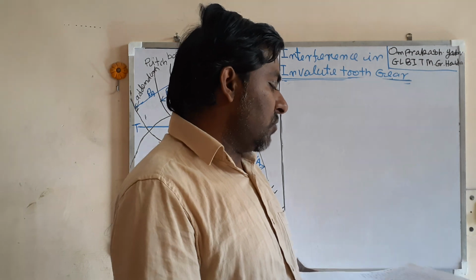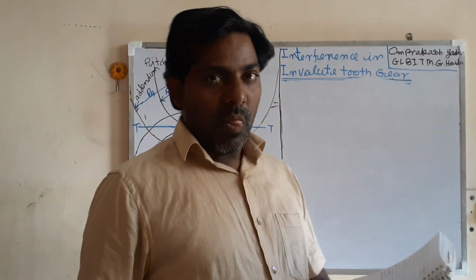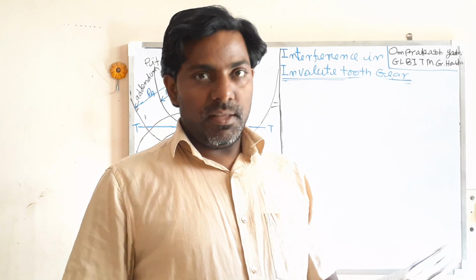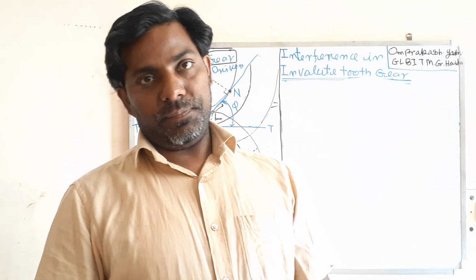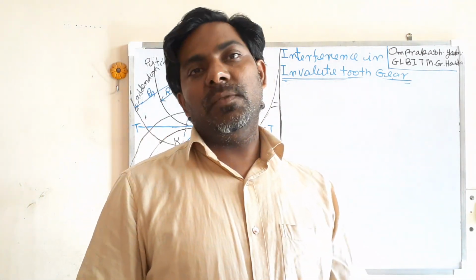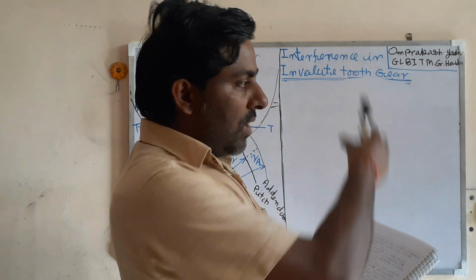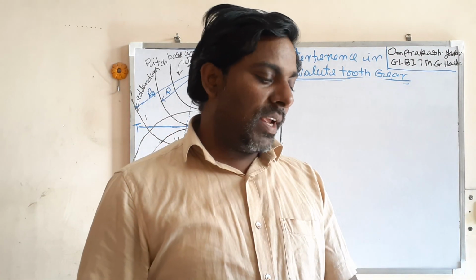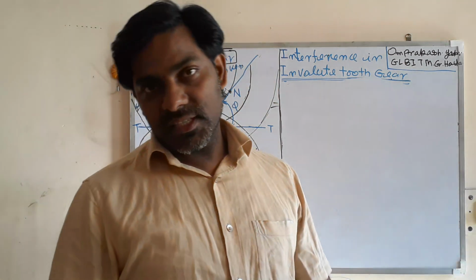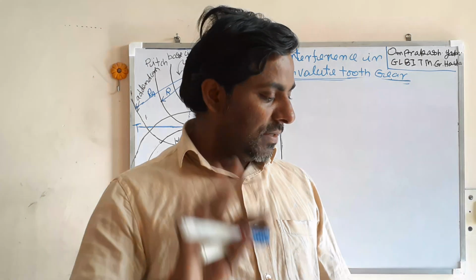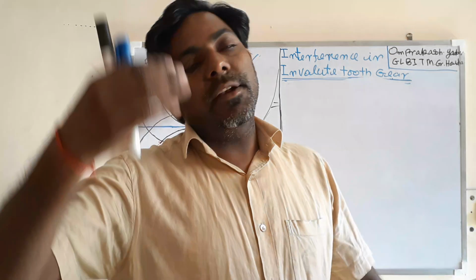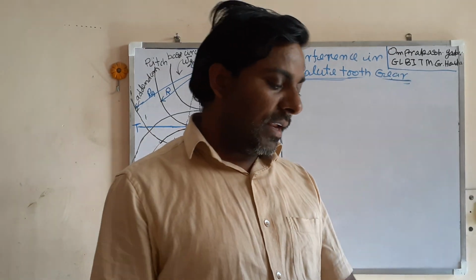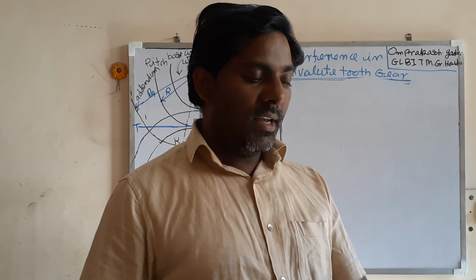So the answer is, what will be the effect? First, the law of gearing will still be satisfied. There is no problem. The pressure angle will increase. If you make two diagrams of increasing the center distance between the shafts, you can understand this. What about the base circle? This is a property of the gear that will not change. Another thing is that the path of contact, arc of contact, and the contact ratio will decrease.